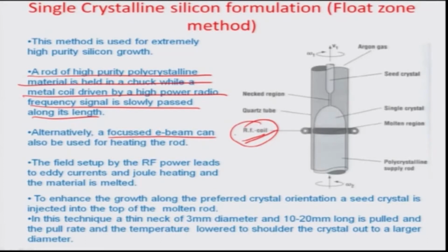But the idea is that a seed crystal is lowered from the top end, as you can see here, and this crystal is the one which causes the growth to happen. And so, whatever liquid is created in this area because of heating, as the rod is being fed inside, would ooze out from here and fill up this region, and this would be a melt, and the seed crystal, what is coming out in this particular area, you are pulling out. So, that is the same constitution as the Czochralski, only the heating here is not a wall mediated heating, but a uniform heating of the material.